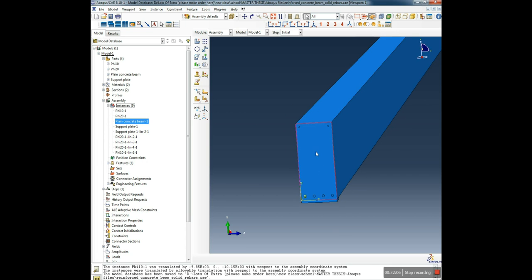And right now we will make every part independent, and so we will merge all the parts in one part. So maybe we don't need to make them independent actually right now. So Instance, and then Merge/Cut. There is a last step here. We click it,